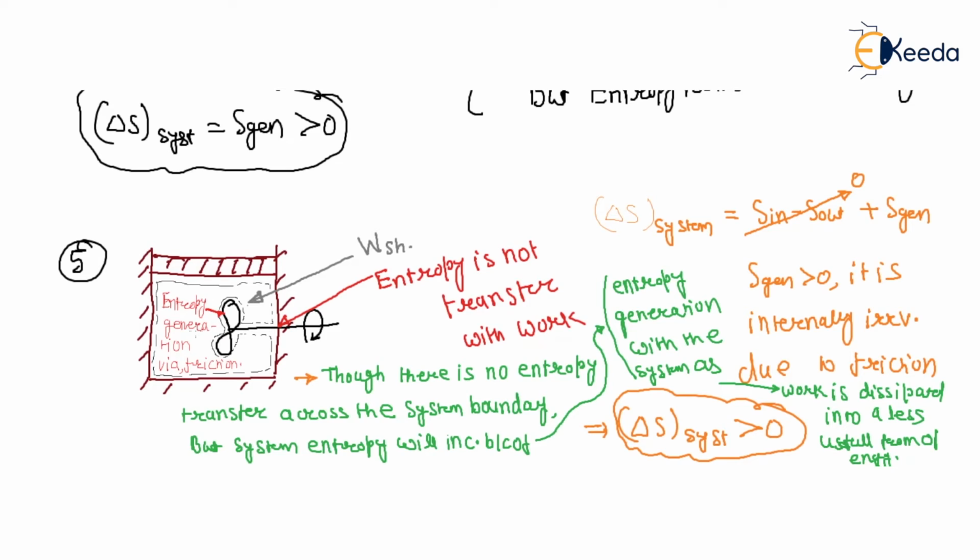So less and less work will be wasted, less and less useful energy will be wasted, so there is less and less entropy generation. The less the entropy generation, the more reversible the process. But there is always dissipation, because there is viscosity. If there is viscosity, there is a chance to dissipate that energy, in the form of work, via friction. So there is more and more entropy generation. Entropy generation tells about the extent of irreversibility: the higher the entropy generation, the more irreversible the process.